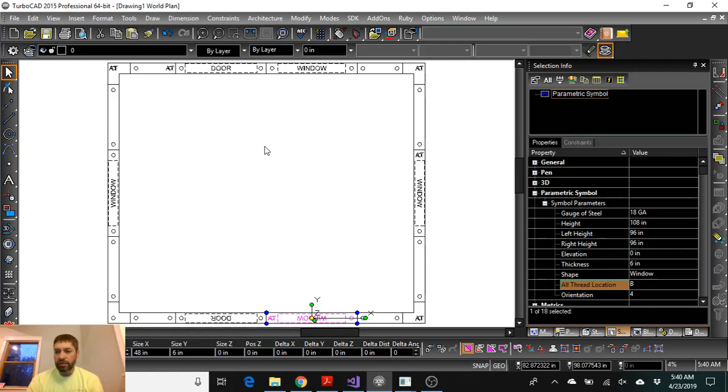It's going to include a count of corners, and a count of all the different components: 2-foot sections, door sections, window sections. It's going to begin a count of all the components necessary to create the all thread at location B of this panel that is of this height. So that's the anchor, any couplings, the all thread itself.